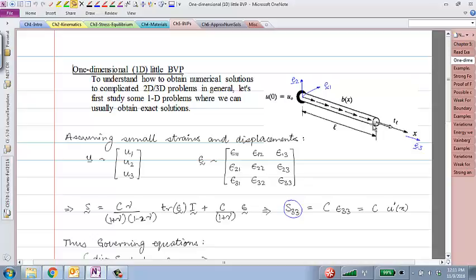So this is a three-dimensional problem where I hope you can see that the behavior will be all along x, all along this x dimension. It's very similar to one of the experiments that we talked about. Anybody remember what experiment I'm talking about to determine material properties? Uniaxial. The behavior is uniaxial in here. The state of stress is not uniform along the bar, but at any point the behavior is uniaxial. If you go to any particular cross section, we are assuming that the behavior is uniaxial.